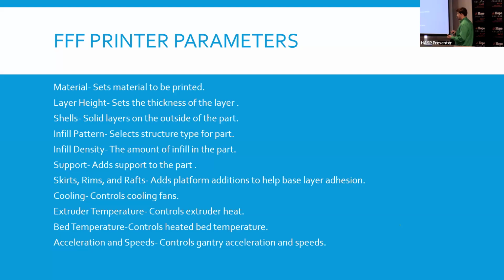And rafts are going to create a large surface area underneath the part. It's built up just like a raft out on the ocean that your part sits on. And it makes it where it sticks directly to that bed. Downside of rafts, though, coming from personal experience, they are hard to get off your part. So they will stick to your part like they were a part of your part.